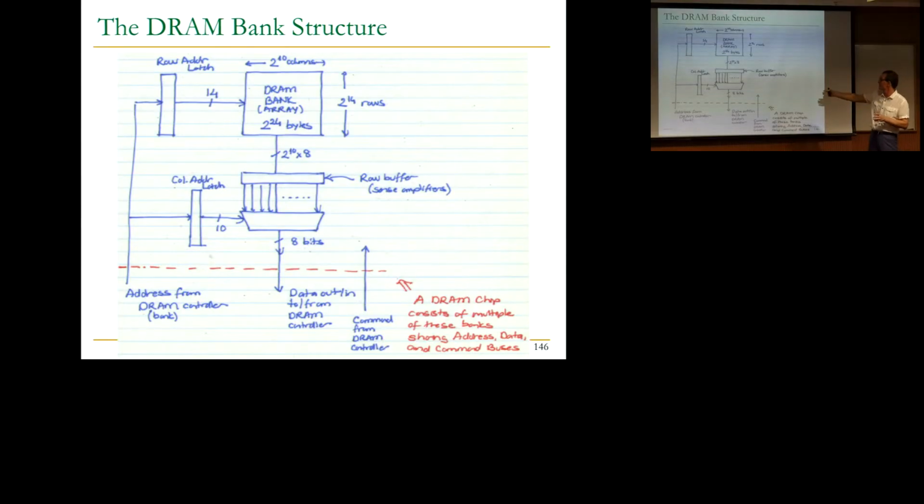But let's assume even if you want a byte, you still need to open the entire row, which is a lot. And that's part of the waste. But it's designed this way. Otherwise, the area cost is very high. Otherwise, you need separate row decoders for every single 8 bits. Yeah, that's a very good point, though. Part of the bandwidth waste is coming from there.